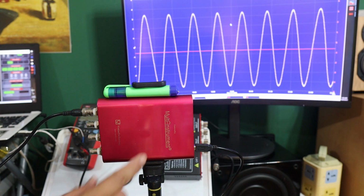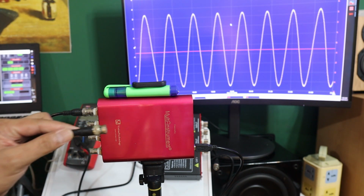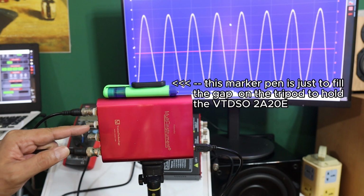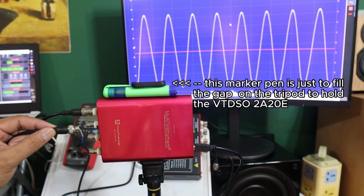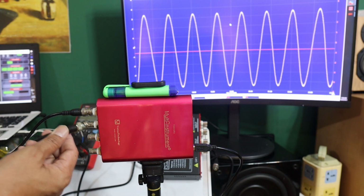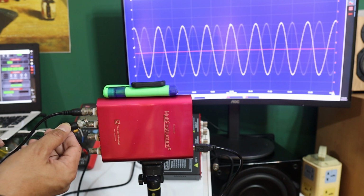I superimpose the DSO2820E with the left signal only. That is the one with the problem, and I remove the right channel input. So this is the right channel input, or the channel B, for the DSO2820E. And what's the signal in here? When I just put the grounding in here, you can see it reduced.